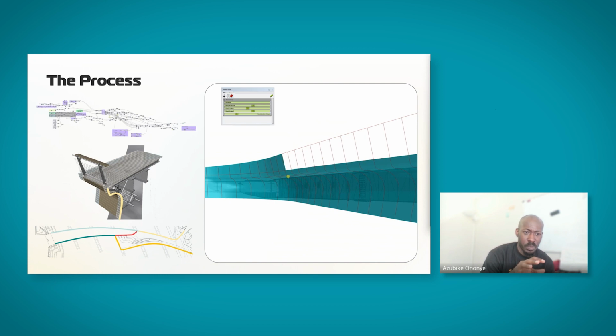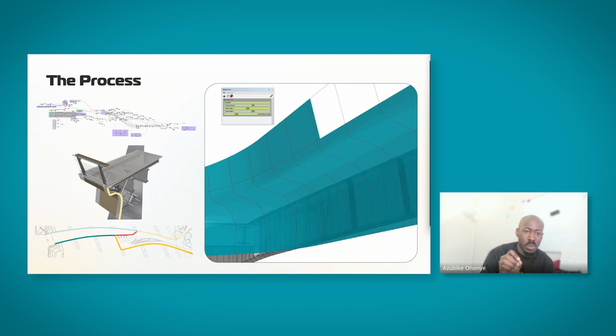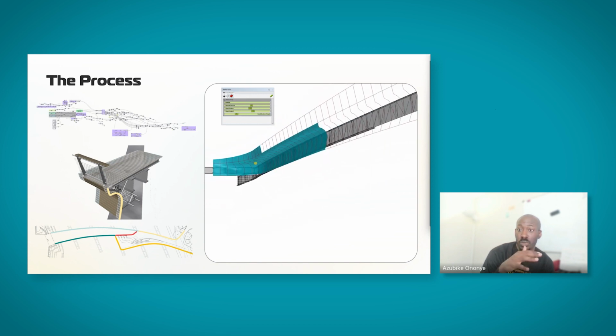it's giving you the ability to adjust, but it's also giving you the distance from the primary structure, because you don't want to be too far, because then you need longer members to connect the substructure for the facade to the primary structure.